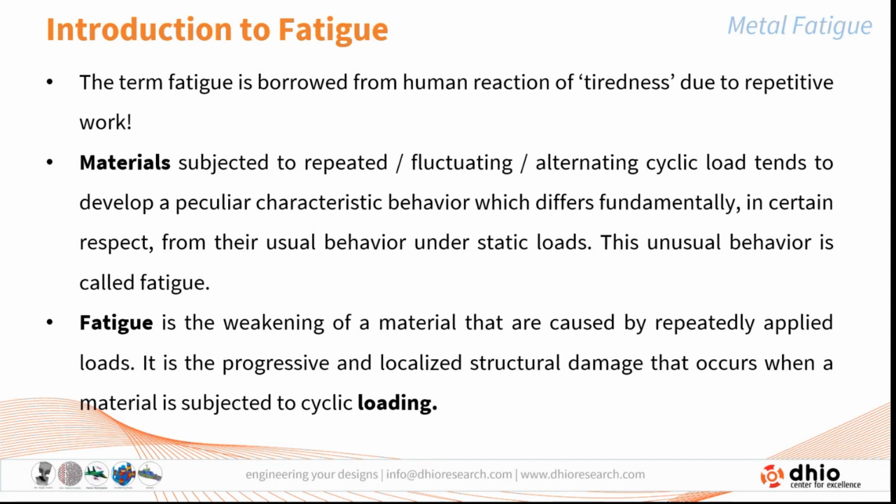The material behaves in a peculiar manner compared with static loading. When subjected to cyclic loading, even loads that cause stress within the elastic limit give the member a tendency to fail due to fatigue. That is because of this peculiar behavior of the material.